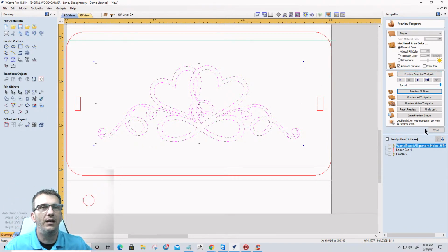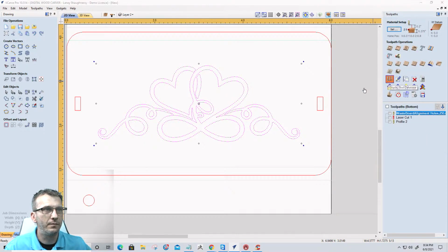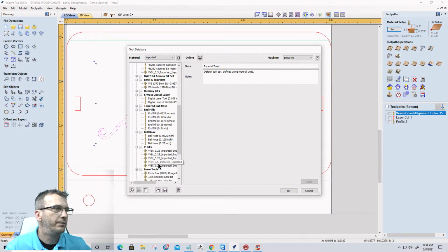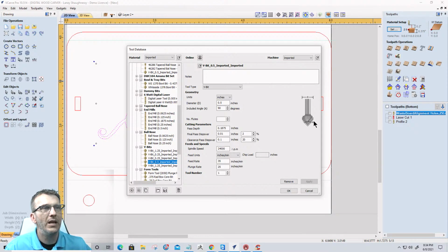Let's look at our tool database here. We can see a graphic. In this graphic, you can see we have our V-angled bit, and then it has a straight cutter on the two edges. We don't want to exceed that cut length because we don't want to get into that straight lip. If we do, then we're going to have some issues with our inlays, especially a V-carve inlay. And we're doing a V-carve inlay versus a traditional inlay because the detail we're working with is very small, and we have some sharp points here and there. So a V-carve inlay is going to be the best for that.